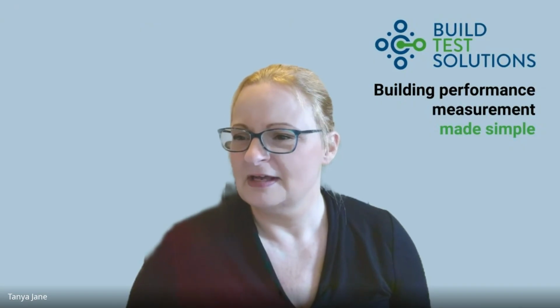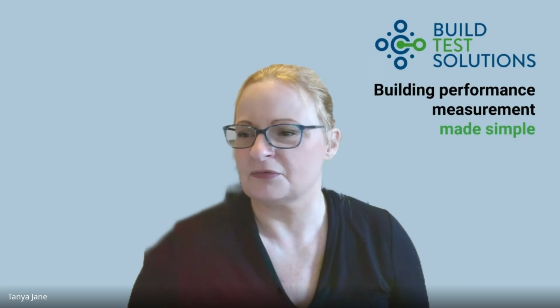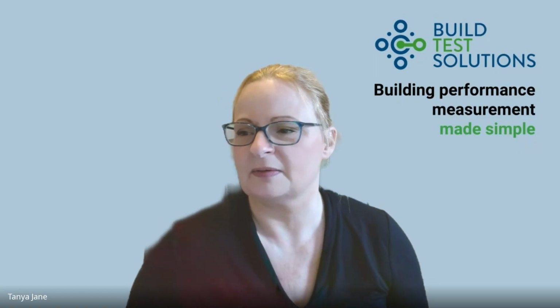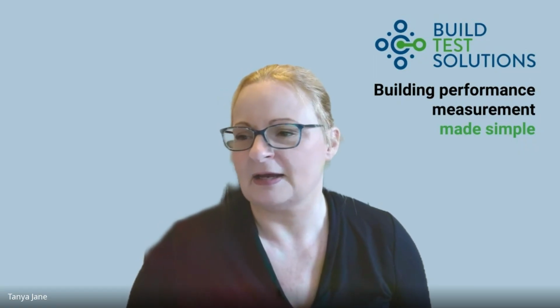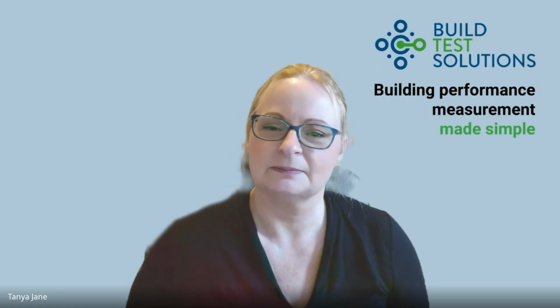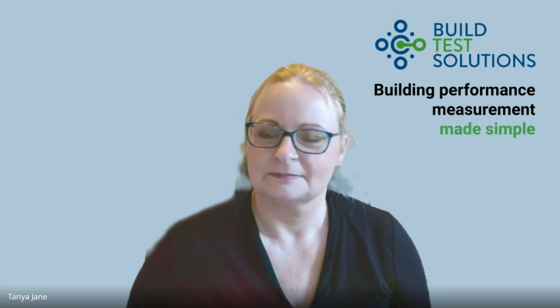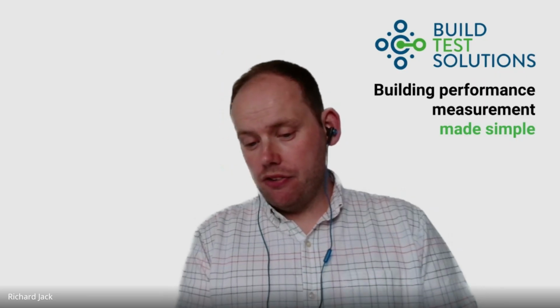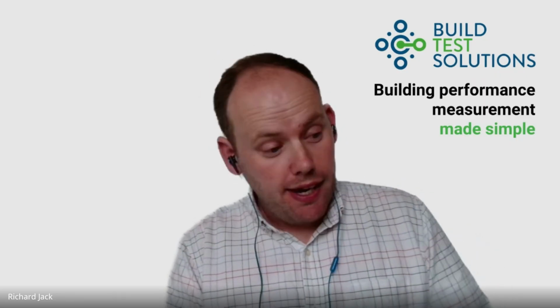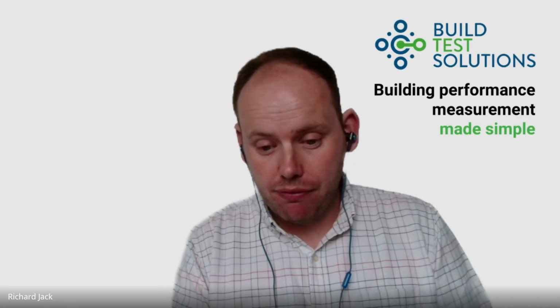I'm going to squeeze one more question in. In retrofit projects, how reliable are heat pump sizing results from IES virtual environment compared to measured heat loss, and how should discrepancies be handled? Yeah, IES is a dynamic model, but it does the same thing where you have to put in a U value for the different components and an amount of air movement. So it is susceptible to the same issues where those underlying assumptions are really variable.